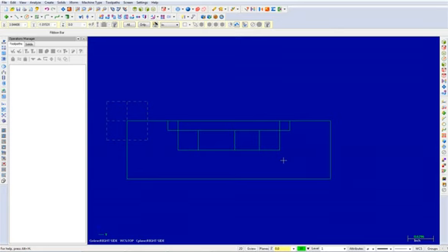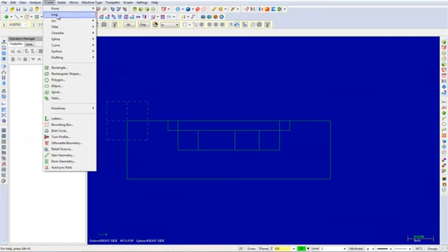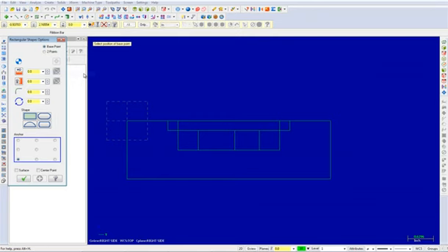Select Create Rectangular Shapes. The Rectangular Shapes Options dialog box will appear. Input a width of 1.75 and a height of 0.75. Now choose the obround shape and pick the option to anchor to center.